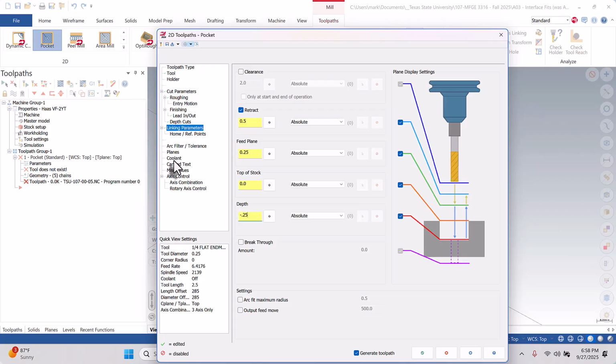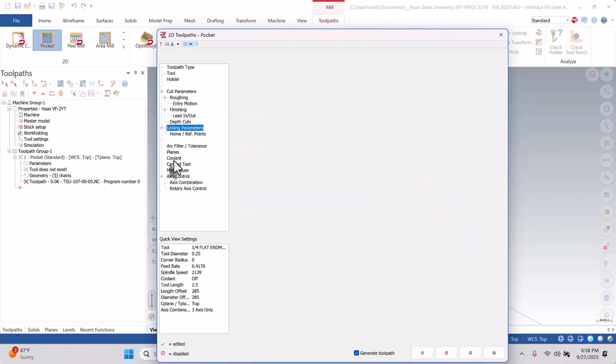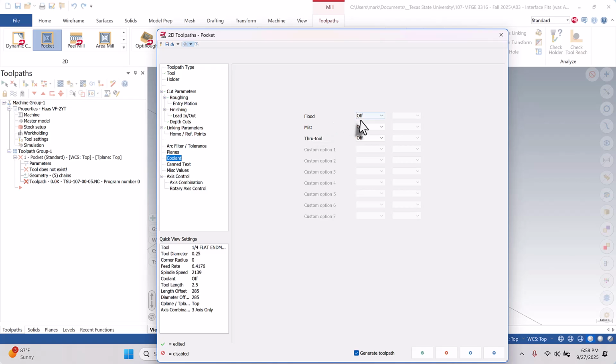And then maybe I'll just come down here and do coolant. And normally for our aluminum parts, we will have coolant turned on. For this ring-shaped material, we'll leave that off. But I'll turn it on just for fun. Or maybe I'll turn it off. I don't want to have that coolant flying around. We can just cut it without coolant, since this is ring-shaped material.